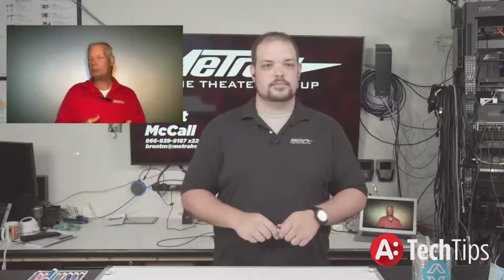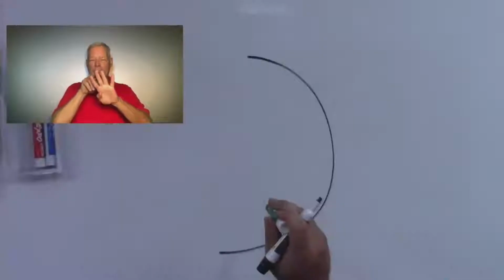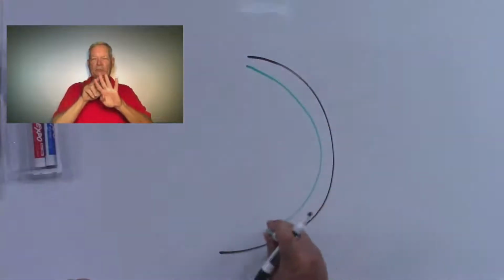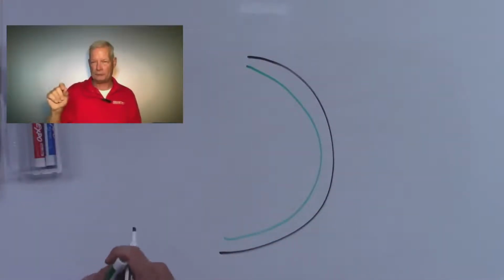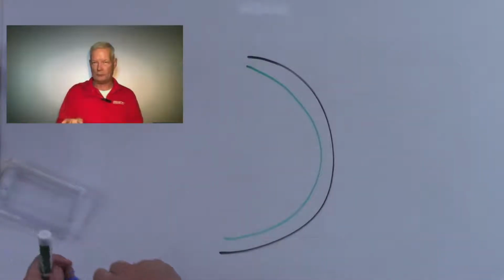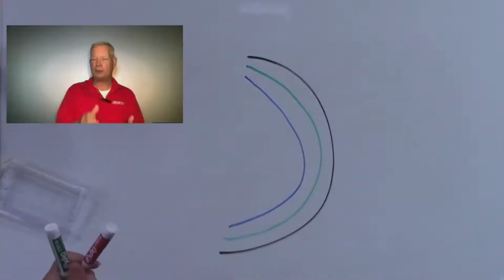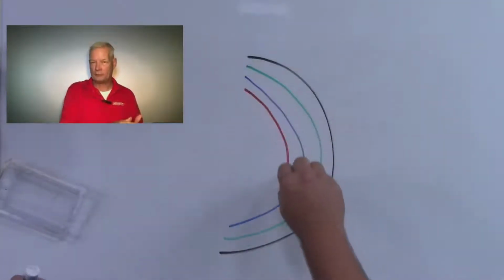The exact same thing has to happen on an HDMI circuit board. So when you've got multiple inputs going into an HDMI board that's then going into a panel or an AVR or whatever, only one of those inputs typically will be a direct path from the jack to the processor. That's the path you want to select whenever possible, because, again, we're back to cumulative errors. It will give you fewer errors.